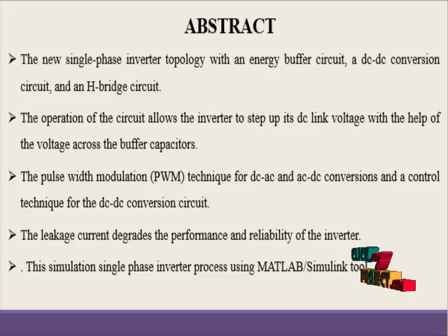So mainly we focus on the inverter's 3 stages of switching and control of the energy buffer level. Firstly, we design the energy buffering circuits in combination with the inverter, where we can use the H bridge circuit level, and we introduce the PWM pulse width modulation converter for the DC to DC conversion circuits.